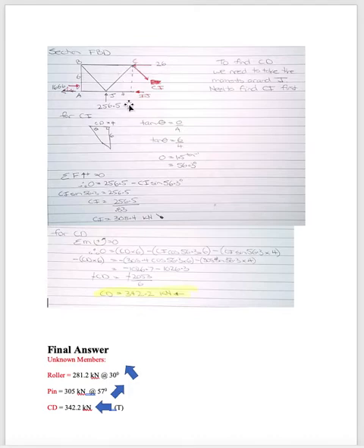That's CI on the horizontal. If I'm actually looking at CI on the vertical, you can see it's only 4 meters away. So then I've got CI 56.3 by 4. From there, simple moments equations to get the reaction in this CD member.